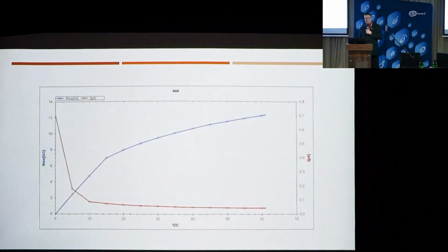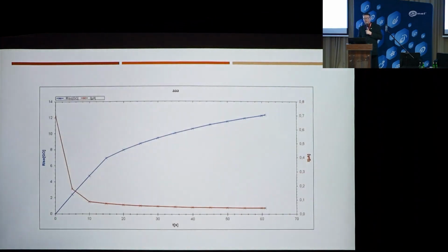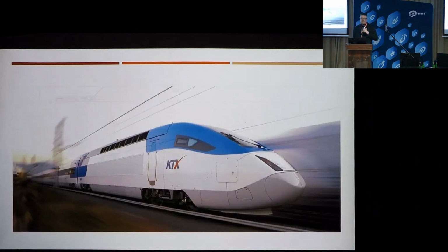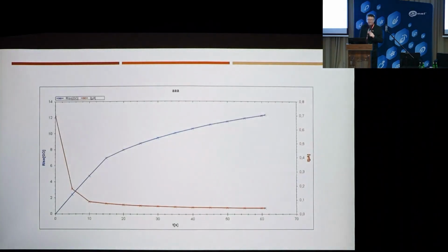So please take a look at what happened after this motor was rewound again. Can you see the difference in the graph? And can you see what insulation resistance value we reached? 12 gigaohms. Here, in this case, the measurement lasted 1 minute. 1 minute because I was calculating the DAR ratio, so even so. And to finish up, ladies and gentlemen, here's an interesting case.